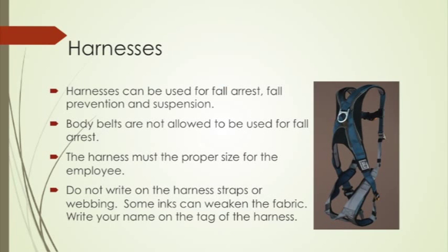Harnesses are a popular option as they can be used for fall arrest, fall prevention, and suspension. Body belts are not considered a harness and cannot be used for fall arrest. The harness must be the proper size for the employee and in good condition.